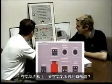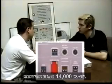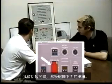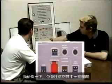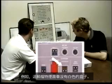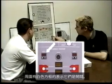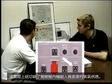On the oxygen panel, when will the passenger oxygen system deploy? Whenever the cabin altitude exceeds 14,000 feet. Could you manually deploy? Sure, I'd lift the switch up and then select the button that's underneath there. As a neat aside here, you'll notice that some of these switches have white boxes around them and some of them don't. For instance, this forward smoke over here does not have a white box, neither does the aft. That means these are not switches. Ones that have white boxes around them are switches. Crew supply switch. That basically just cuts off the oxygen to the crew masks in the cockpit.